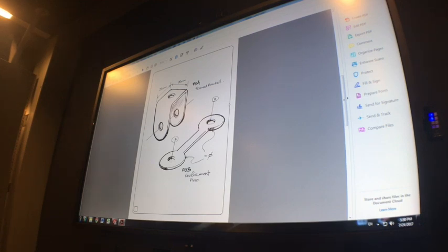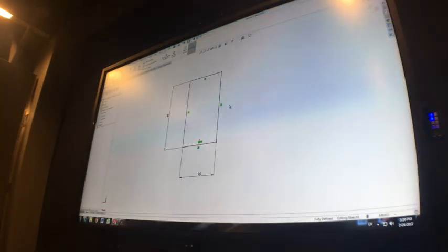When you're making something out of sheet metal, or it could be acrylic as well that's heat bent, anything like that, the key design feature that it requires in your 3D model is a consistent wall thickness. From the outside to the inside, going around the radiuses, around the curves, it's the same thickness. So that's why here with this sketch, it's much easier and more efficient, instead of drawing a separate shape on the inside, to just offset the outside area.